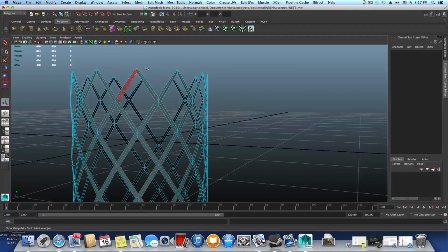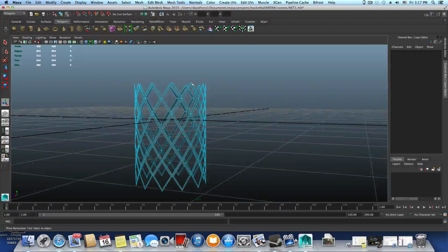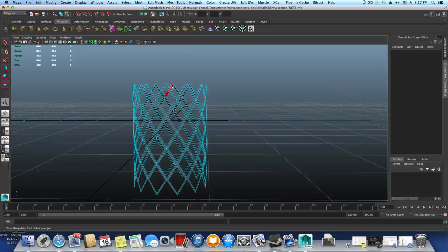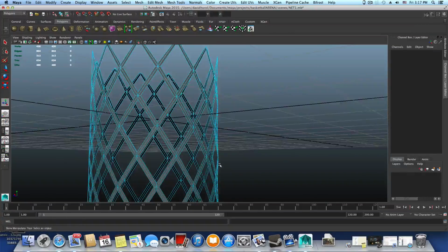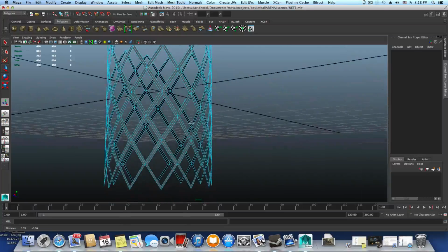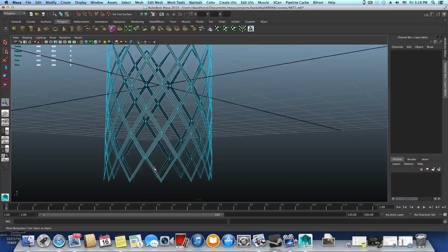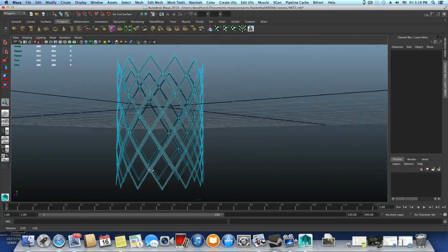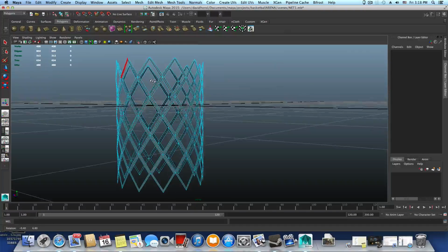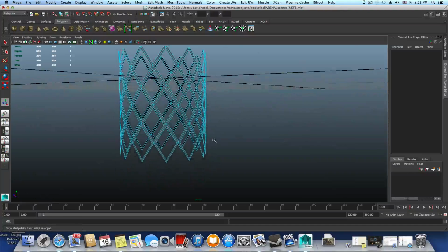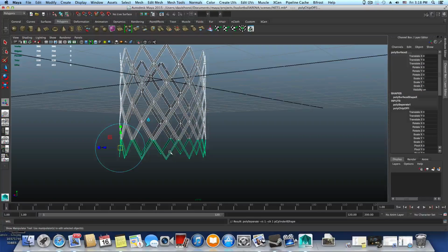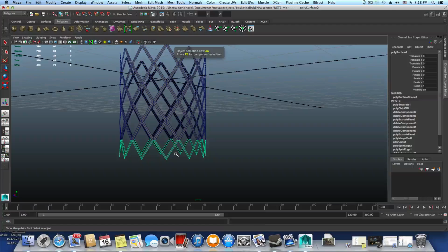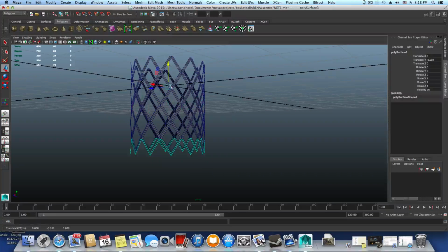Now this is the problem. I don't like these pointing ones. That means that I had to delete those earlier, okay? And those triangles up here, those that are not there. So in order to fix this, these are already aimed here, and I need to get a result that looks similar to these bottom ones. So I'm gonna delete those. Just like that. Gonna grab all those faces down here, mesh, extrude, yeah, let's extrude them. Press F8 3 times, grab this one, Control D to duplicate it, move the duplicated copy over here.